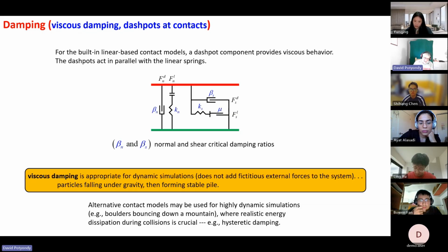And then the last thing is there are other damping things which I mentioned at the bottom here. Again, for all the work that you guys are doing, you're always concerned with quasi-static loading, and so you can always just use the local damping. The only thing to remember about that is that every particle has its own local damping coefficient, and by default, it's 0. So you're always going to end up saying, oh, the balls are going to have a damping coefficient of 0.7. So you have to actually give that command. Otherwise, there's no damping. By default, there's no damping. Okay.